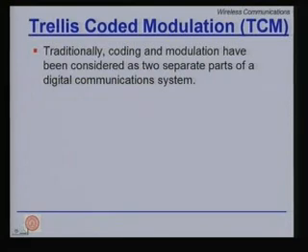So, BPSK performs better in additive white Gaussian noise than QPSK, for example. Right? There also the different modulation schemes have been designed that for a given power, what is the best noise performance you can get. Surprisingly, the objective of error control coding is also to overcome the effects of noise.